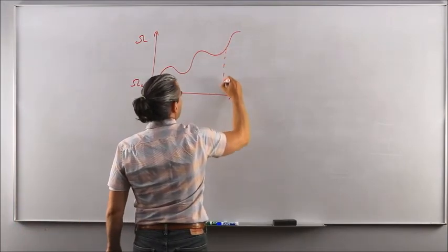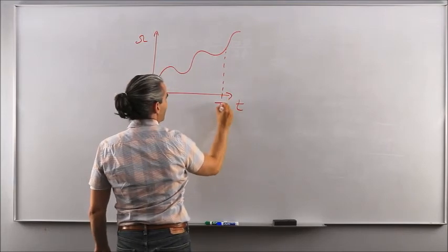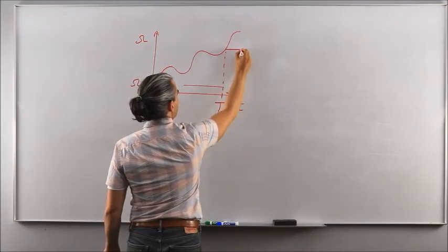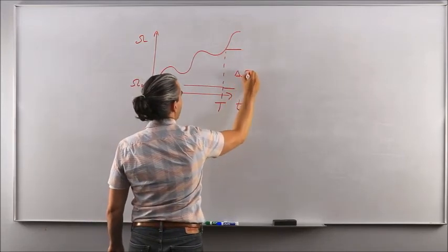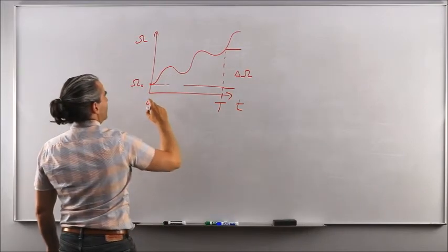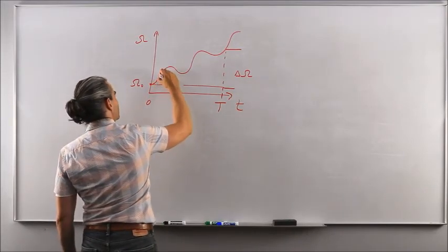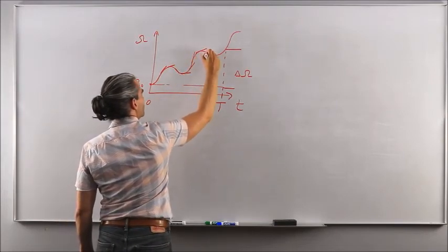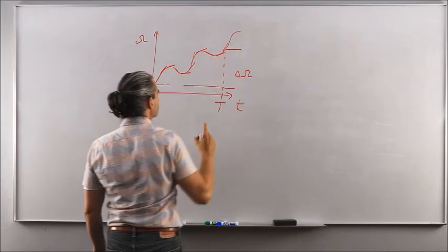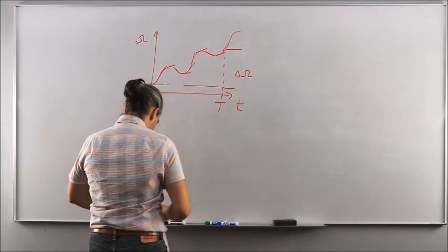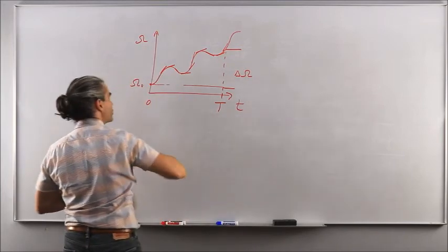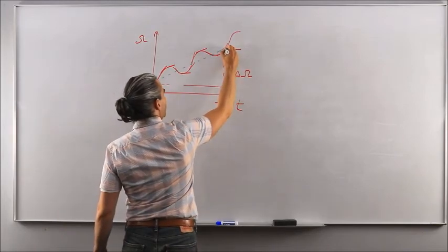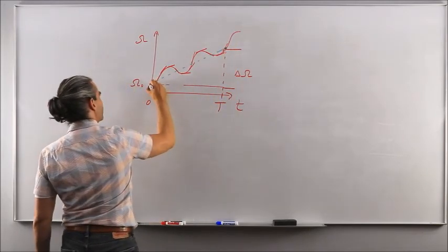If that is the value at t equal 1 orbital period later, then again you know that the net change here is your secular variation. The instantaneous rate of change is essentially the slope along the way that you get directly from the Gauss Variational equation, like this. But another thing you can obtain is the average rate of change. So you draw a line between the final value after 1 orbital period later and the initial value here.